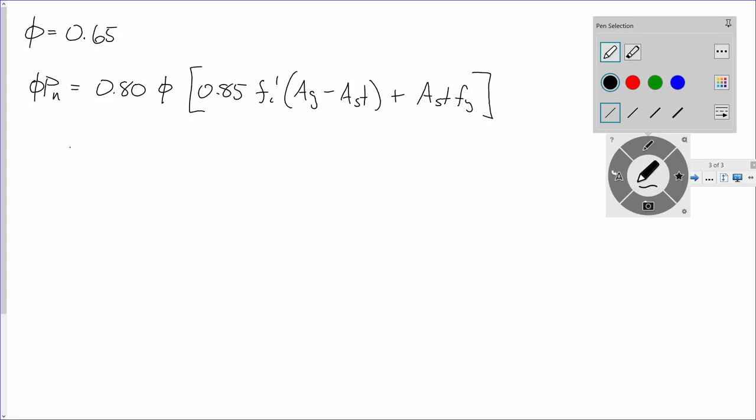So we've got 0.8 times 0.65 times 0.85. f'c is 4,000 PSI, I'm just going to go ahead and write 4 ksi.